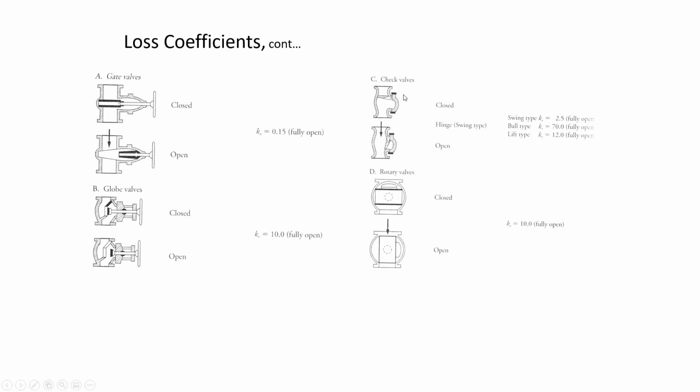And so they put check valves so that water can flow one direction through the pipes, meaning out to the street. But then when the sewer pipe is full and it would otherwise be going back towards people's basements and shower and bathroom, the check valve swings closed and prevents that sort of damage. So you can see that there's several different types of check valves.